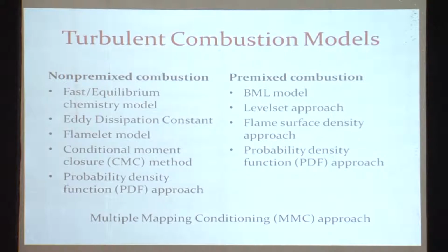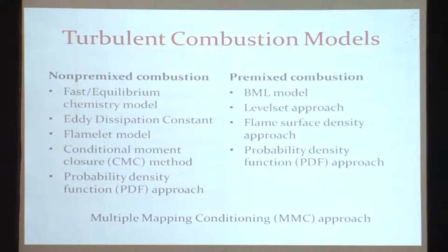So here are some lists of the different turbulent combustion models that could be applied to non-premixed and premixed combustions. So there are plenty of models available for non-premixed combustion, like the fast and equilibrium chemistry model, eddy dissipation concept, the flamelet model, and conditional moment closure method. Similarly, in premixed combustion, there are BML model, level set approach, flame surface density approach, and PDF approach. The PDF approach can be used for both of these regimes, non-premixed and premixed. So it offers an inherent advantage that helps it to apply for any kind of flame.